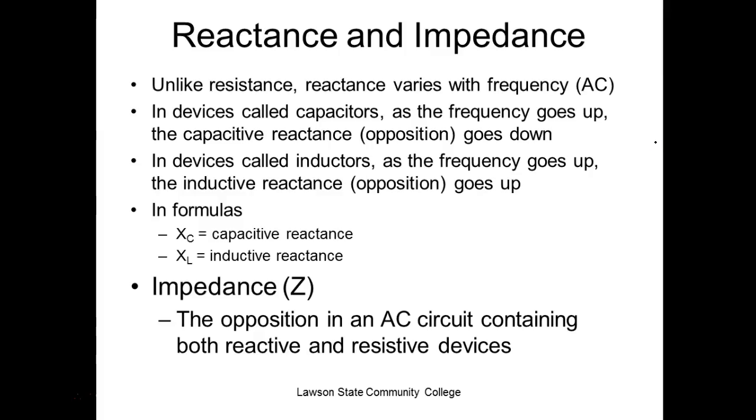Reactance. Now we have to talk about reactance in this class. Whether you really understand this in this class is not extremely important. You're not going to have to do any math, but you need to understand what's going on. Unlike resistance, reactance varies with what? Frequency. So reactance only comes into play in an AC circuit. In devices called capacitors, as frequency goes up, capacitive reactance goes down. In devices called inductors, as frequency goes up, inductive reactance goes up.